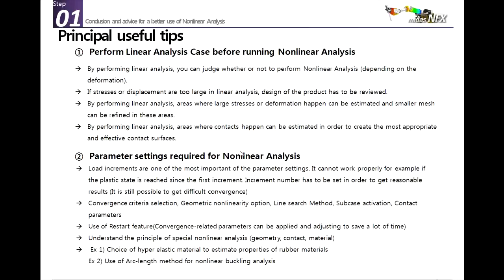So I have a lot of tips because nonlinear is not difficult, but you need to consider a lot of options. So first, perform a linear analysis case before running nonlinear analysis. By doing that, you will be able to judge whether or not you need to perform nonlinear analysis, depending on the deformation.